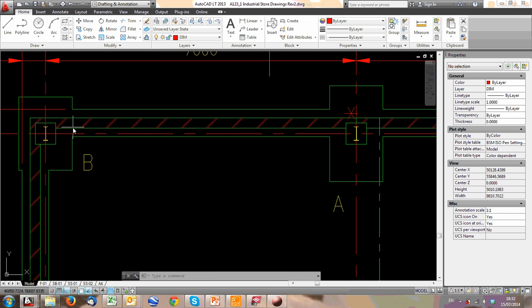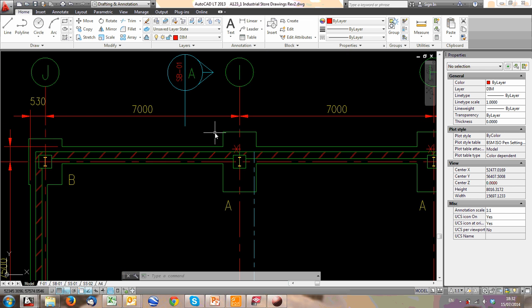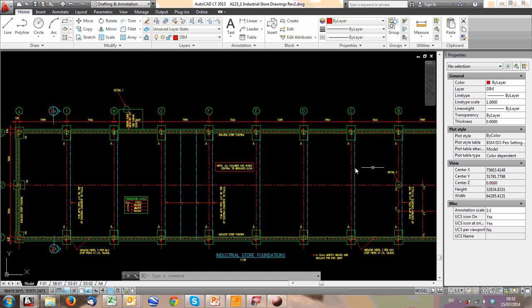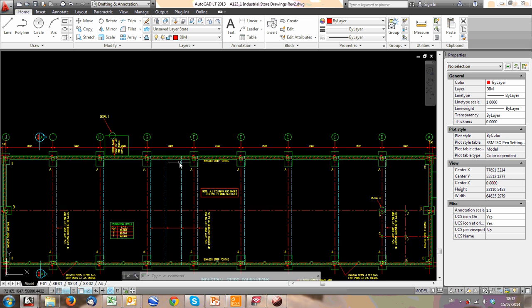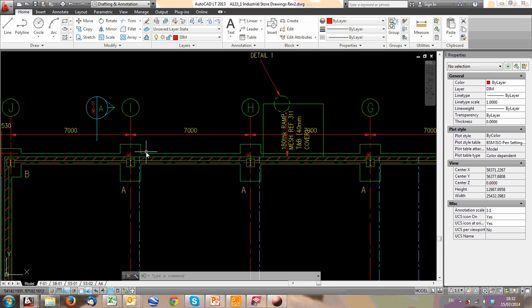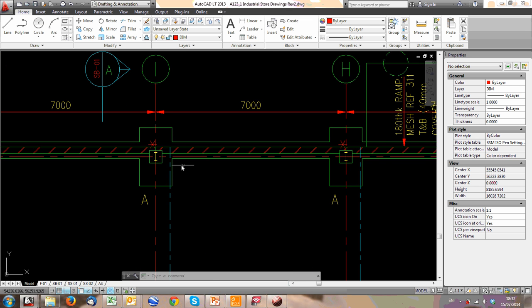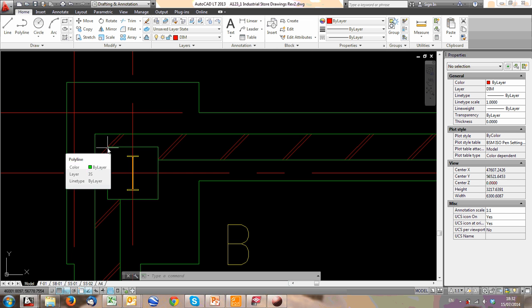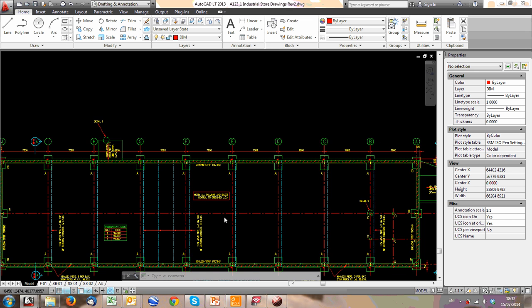But before we get to that stage, the way you could draw this would be more or less the same as we learned in the second and third lessons, by simply creating one column or one base, then creating a block of this, and then creating an array across, or mirroring it. Especially because there's so much repetition, you could create a block with the next bay of brickwork and repeat that throughout. Otherwise, you could draw the brickwork by drawing all the columns, offsetting two rectangles from this point here to the far corner by 115 mils each way, and then trimming the lines out between the columns. So you could get that relatively quickly.